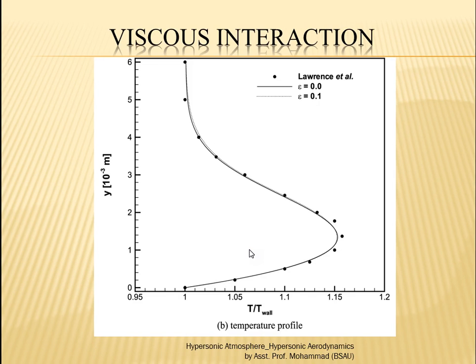Now this high temperature affects the viscosity. You know very well that fluid viscosity is affected greatly by temperature. For liquids the viscosity comes down, and for gases the viscosity goes high with high temperature. So a high temperature will cause a high viscosity there. This high viscosity will further cause viscous dissipation, so a further increase in temperature. It is perpetual: they start giving positive feedback to each other. So a very high temperature is anticipated in this particular region.